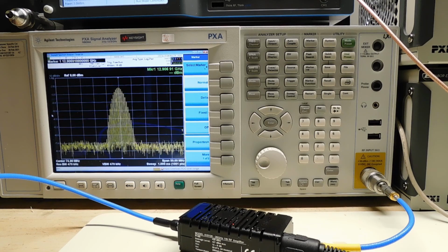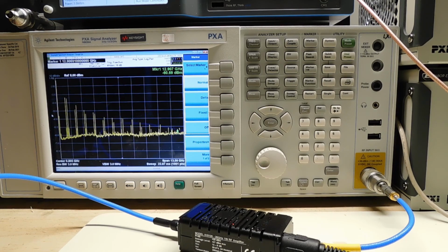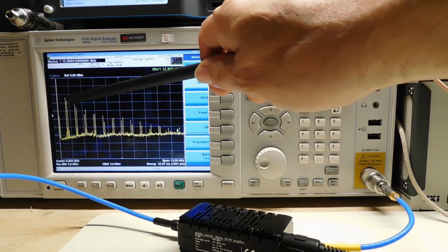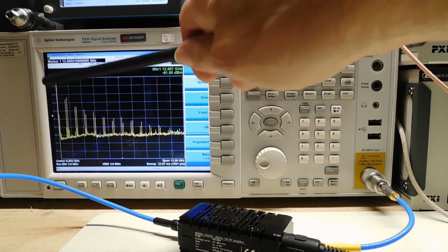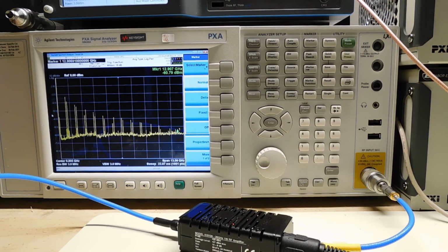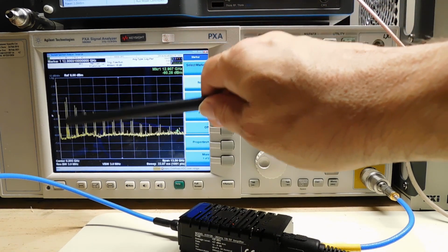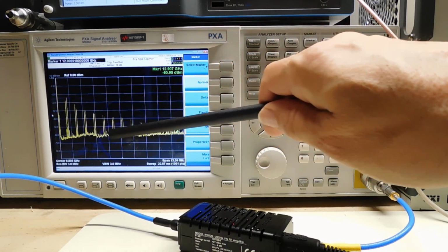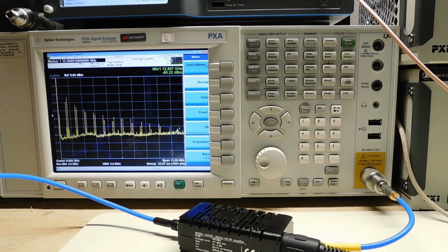So this is a 13 gigahertz spectrum analyzer, so the sweep we see going across there is all the way up to 13.5 gigahertz, I believe. Right at this side we can see the 75 megahertz fundamental frequency that I created, but also because our clock frequency is set to 1 gigasample per second, I get plus or minus 75 megahertz at 1 gigahertz, 2 gigahertz, 3 gigahertz, 4 gigahertz, 5 gigahertz, 6 gigahertz, and so on. And these are our Nyquist bands.